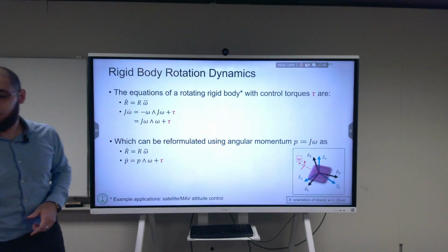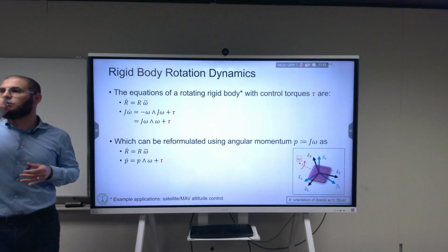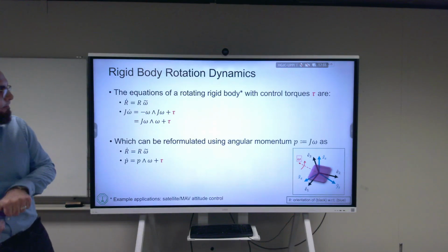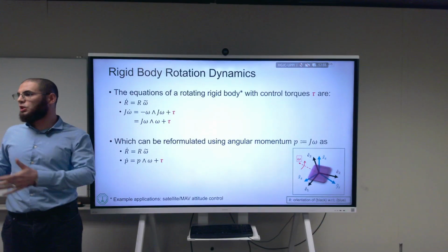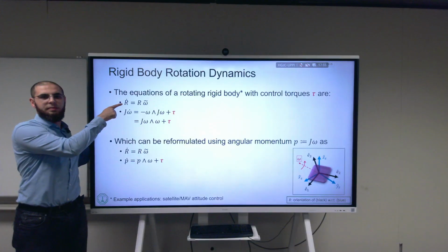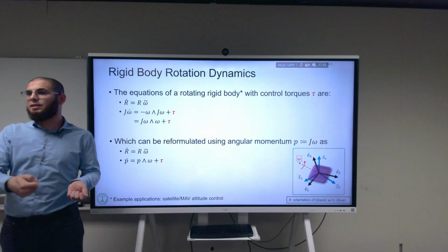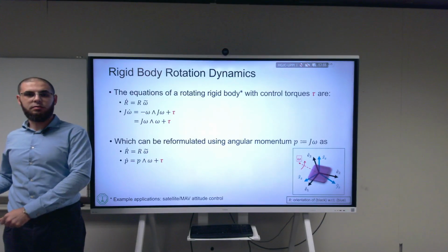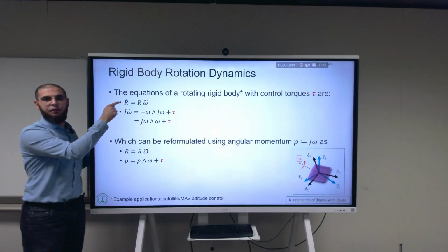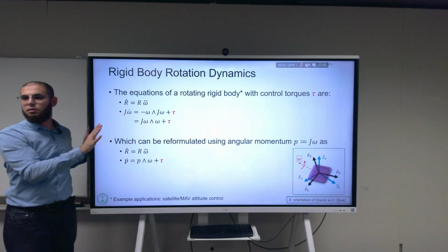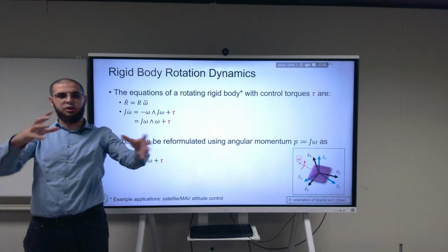We're going to have our PD example that corresponds to SO3, and this is an example of a rotating rigid body. The equation of motion that psi dot is equal to velocity, so the rate of change of position is equal to velocity, on rotations looks like this. Make sense? And the equation that says rate of change of momentum is equal to applied forces on SO3 looks like that. Rate of change of angular momentum. J here is a constant. It's the moment of inertia of this rotating body. This body is not moving, it's only rotating in its place.